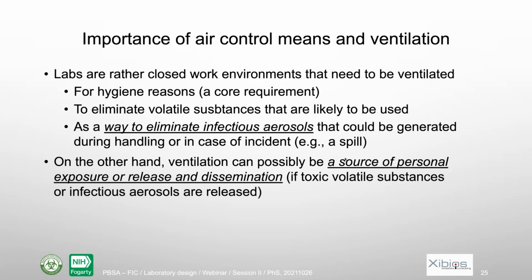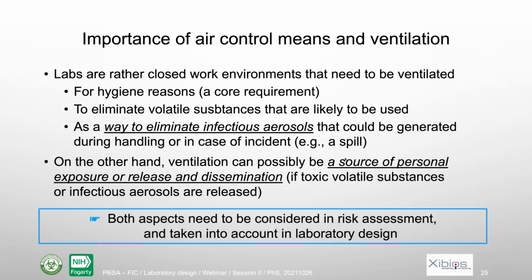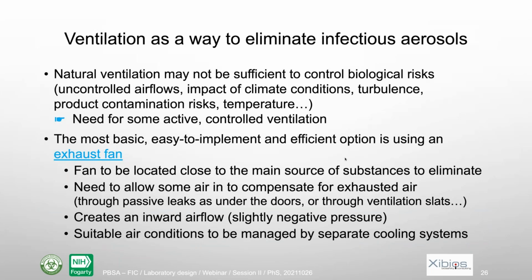So that means that we need some ventilation, but we need to be very careful when we define the solutions that we want to put in place, because we want to do it so that it's well ventilated, but without exposing people either inside of the lab or outside of the lab. So, as you know, natural ventilation may be used in a lab as a very basic measure, but most of the time in biosafety lab, it's not something that should be done.